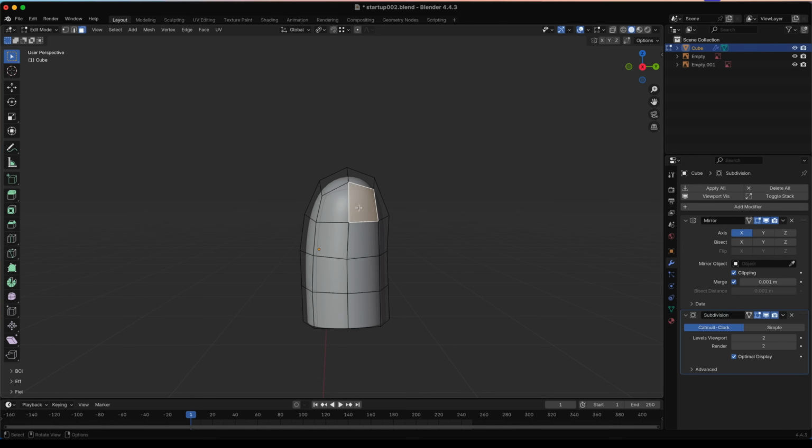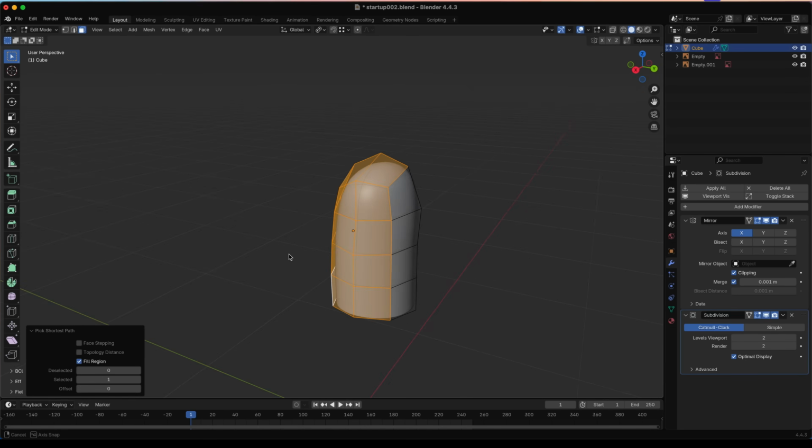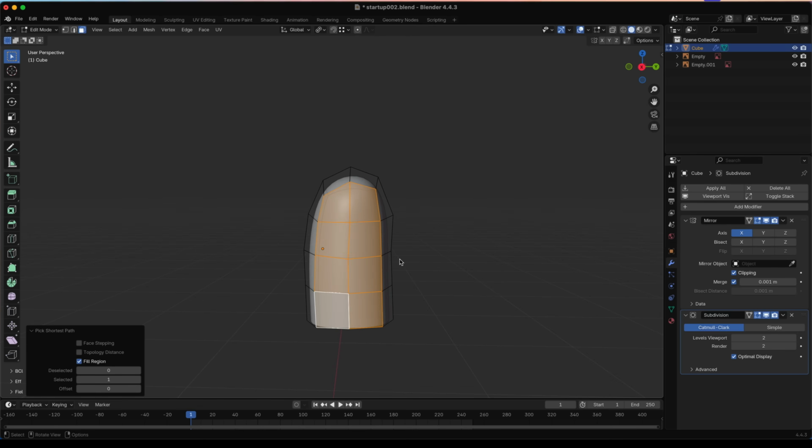To actually add our sleeves, we need to cut a hole in the mesh, and then we need to extrude that hole out. So let's go ahead and select this polygon right here. This is actually a cool trick. You can click one polygon and then go to the other corner of all the pieces you want selected and Command or Control and Shift click that, and it will select everything on that grid line in between those. So that's pretty helpful.